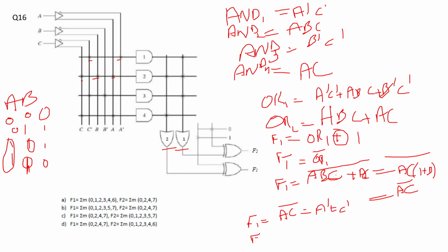Now you have to write the sum of product forms. You can easily write it. So for all the terms that contain 0, it's 0 1 2 3. So summation 0 1 2 3, and C bar is the last term; 0 1 2 3 is already covered. 4 and 6 are the other terms, so this is equal to 4 and 6.